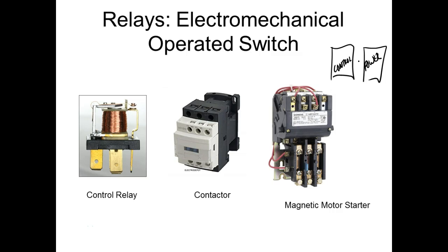So the big thing about using hardwired control circuits like that is if you're going to change something, you had to do what? No, you didn't change the program. You had to rewire it. So back when carmakers started trying to move into automation, they did it with relay logic. And really, they had two lines. They had one they were running this year, and they had the other one they were rewiring for next year. Now we don't do that.